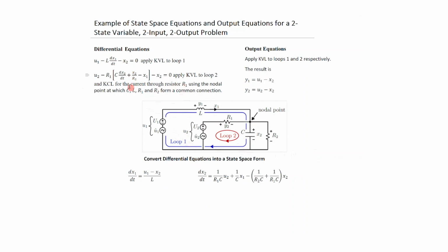So here are your two equations, the state variable x1 and state variable x2. But typically, we're interested in putting this equation in the standard form where you only have dx1/dt on one side and all the variables and other things, inputs, on the other side. Similarly here. So this is basically what I've done out here. I've simplified the equation such that dx1/dt is on this side, and you get this expression, and dx2/dt looks like this.